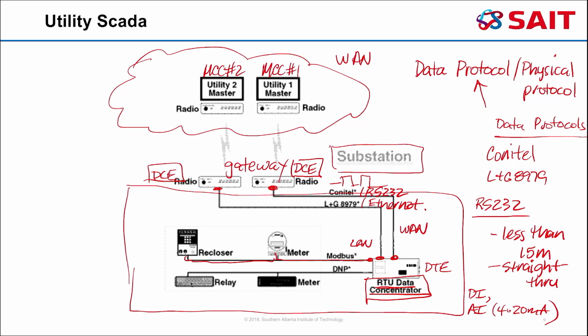And an example that we've looked at that was multi-dropped was an asynchronous serial connection, not RS-232, but RS-485. So this is where we could say that this is Modbus over RS-485, which would give us multi-drop.